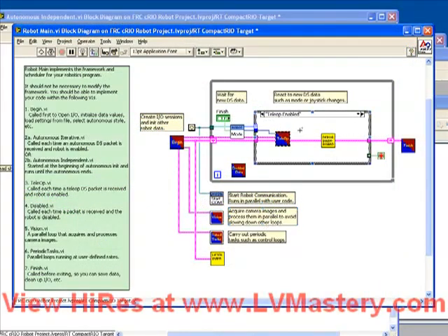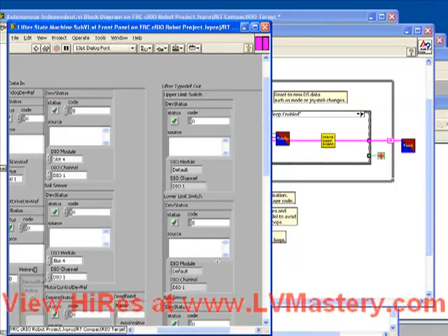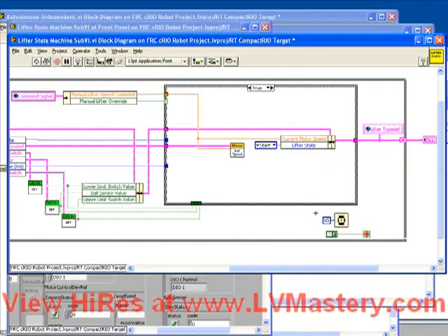So, to recap, we took the state machine which we created in a previous exercise to control a theoretical mechanical lifter out of the Tele-Op.vi and turned it into a sub-VI which runs at the root of the robot main. The reason for that was so that we could ensure that it had consistent timing and ran without a lot of other things slowing it down. Then we added a global variable which made it possible to export the values in its internal typedef so that they can be read by other VIs and by our debugging dashboard.